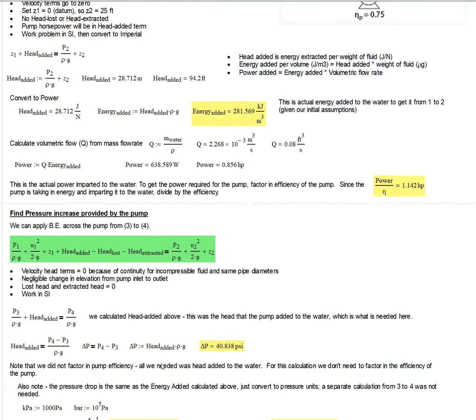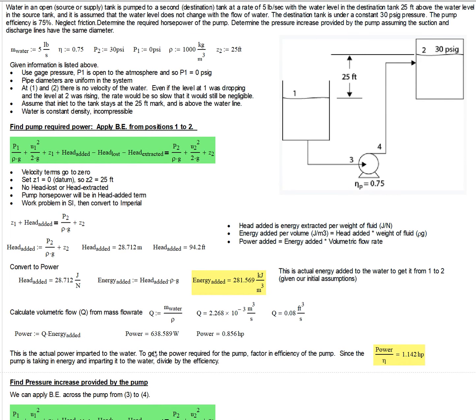So that's the application of Bernoulli's equation to calculating the pump power and the pressure increase across a pump required to move water from one tank to another pressurized tank at a higher elevation. Some simplifying assumptions to make it a little easier. Specifically, we're neglecting friction, but that's where we're starting, and that's how you do these calculations.